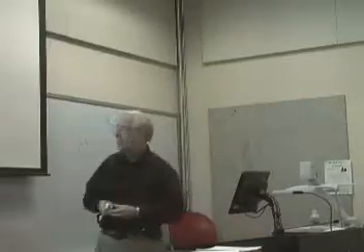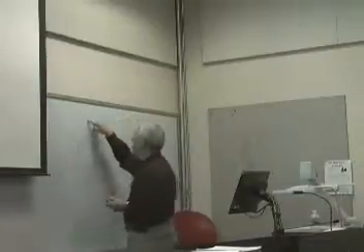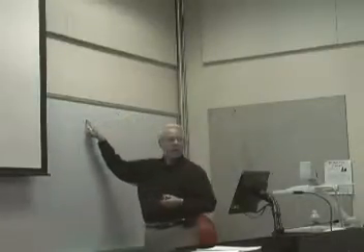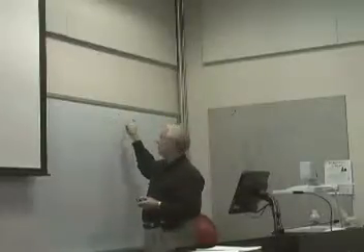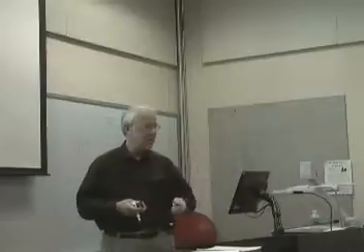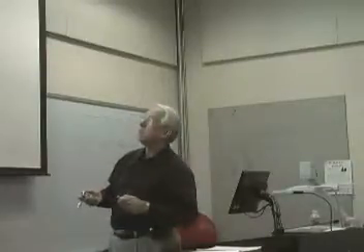Now here we are using, if we go with a quadratic instead of a linear, so we're now going to say, instead of 2 elements, assume that I have only 1 element, and that 1 element consists of 3 nodes. So if I get rid of this, and I get rid of that, and I just have 1 element, I would now have a 3 by 3. So I can write expressions for a quadratic. That's what shows up right here.